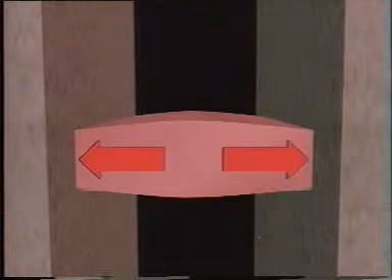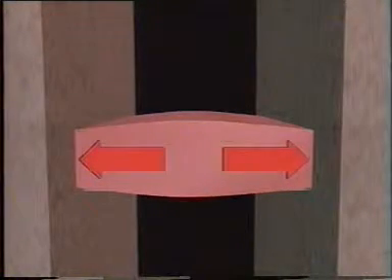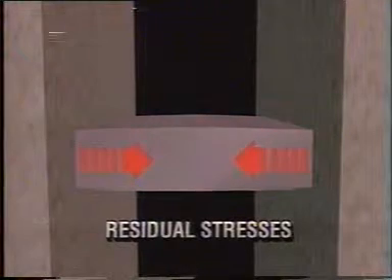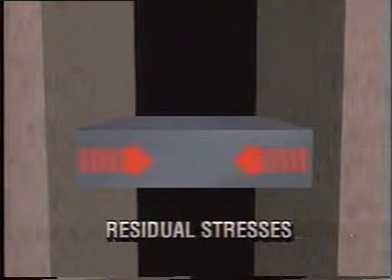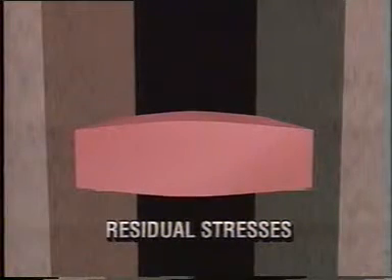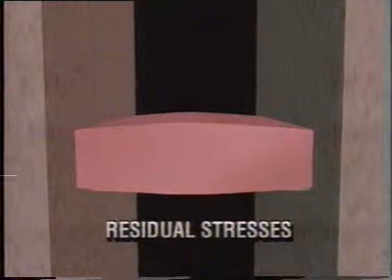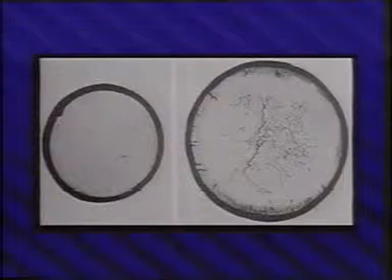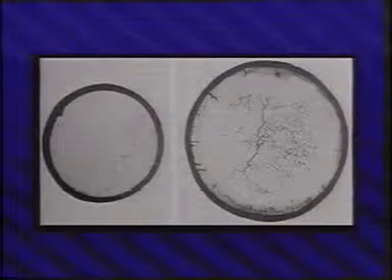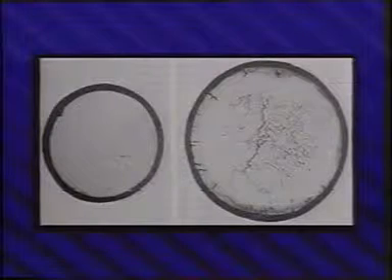When hot, compressive yielding may result, and during cooling, the compressive yielding, in turn, causes tensile residual stresses from the thermal contraction. Repetitive thermal cycling can result in fatigue crack formation and propagation each time the metal cools to the lower temperature. The restraint to the thermal expansion may be external, mounts for pipes, exhaust manifolds, or other rigid structures.